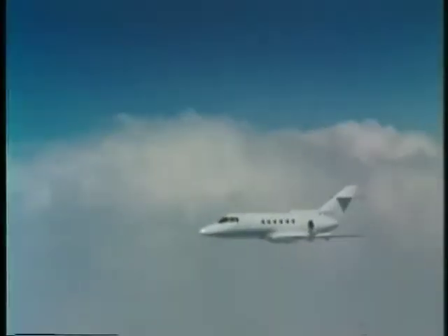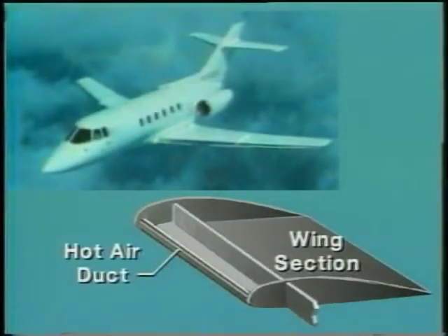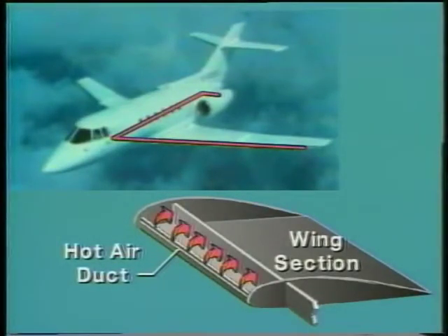If the ice is too thin to break away cleanly, it may refreeze, leaving a space between the ice and the wing. Further attempts to de-ice the wing may be ineffective because the boots inflate within the cavity and don't break the ice. The second type of airframe ice control is the anti-icing system found on turboprop and jet aircraft. This system uses heated engine air routed to the leading edges of the airfoils to keep them above freezing.